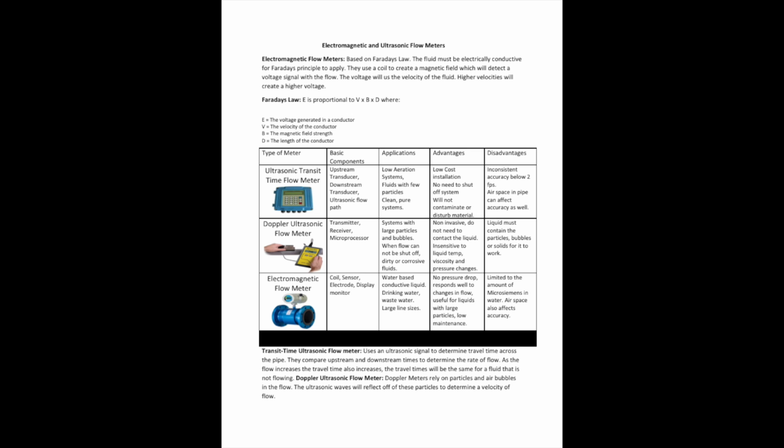We also include Faraday's law of electromagnetic induction and list the variables and their meaning. Faraday's law is the governing principle behind electromagnetic flow meters.